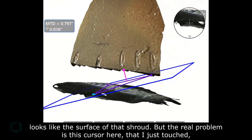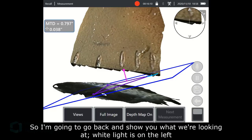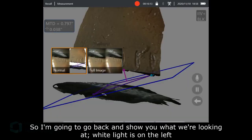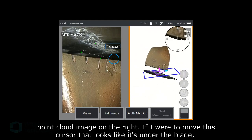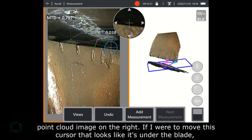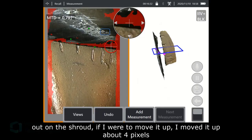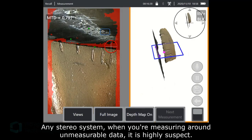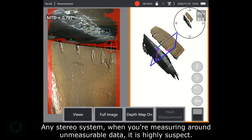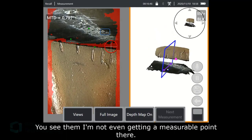But the real problem is this cursor here that I just touched and made active is on the blade and not on the shroud. So I'm going to go back and show you what we're looking at. White light image on the left, point cloud image on the right. If I were to move this cursor that looks like it's under the blade and out on the shroud, if I were to move it up, I moved it up about 4 pixels, and you notice it's around unmeasurable data. Any stereo system, when you're measuring around unmeasurable data, it is highly suspect. And so you see that I'm not even getting a measurable point there.